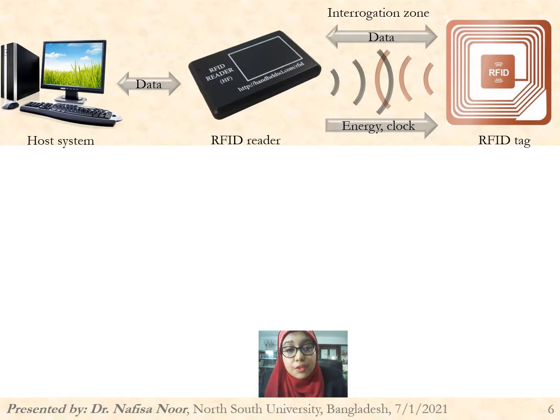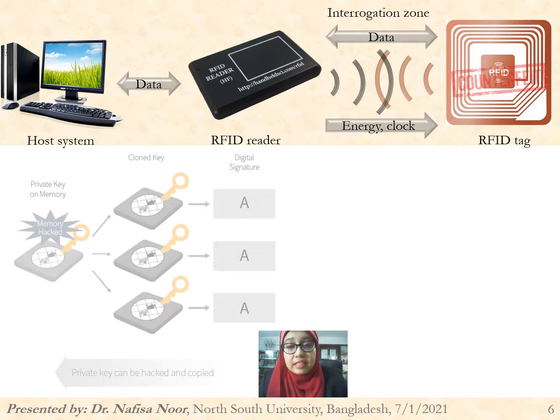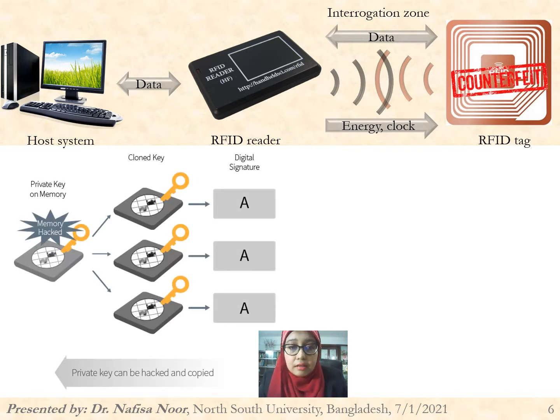As a solution to this problem, we can install chips to these hardware devices for providing security. The traditional way is to store a permanent key in a memory of the RFID tag. But the problem of the permanent key storage is that if the tag is stolen by an attacker, the attacker can directly measure all the permanent keys using the advanced reverse engineering tools and microprobing attacks, and thereby the attacker can produce counterfeit or clone chips.